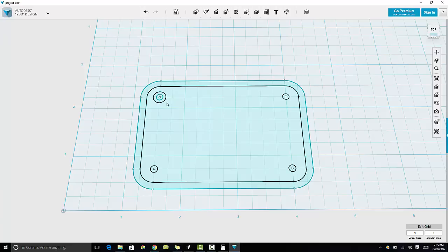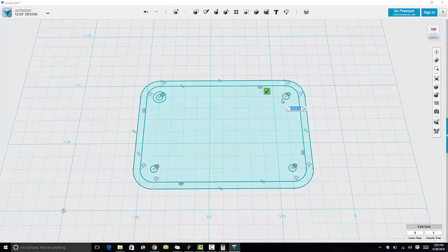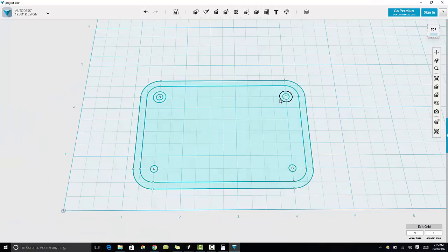So we want to achieve good adherence between each layer, and to make sure we have good strength, it is good to have more surface area for our part. If we went with thinner walls, they would probably break apart really easily, because although 3D printing bonds the layers pretty well, it's still not really good. So it's a good idea, if you want to make these walls maybe even a little bit thicker, to go right on ahead. Not a bad idea at all. So enough babbling. We'll continue on with what we were doing here, 0.06.